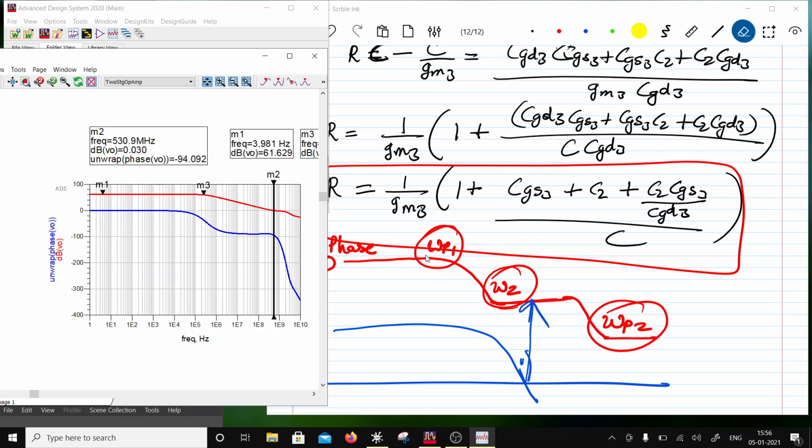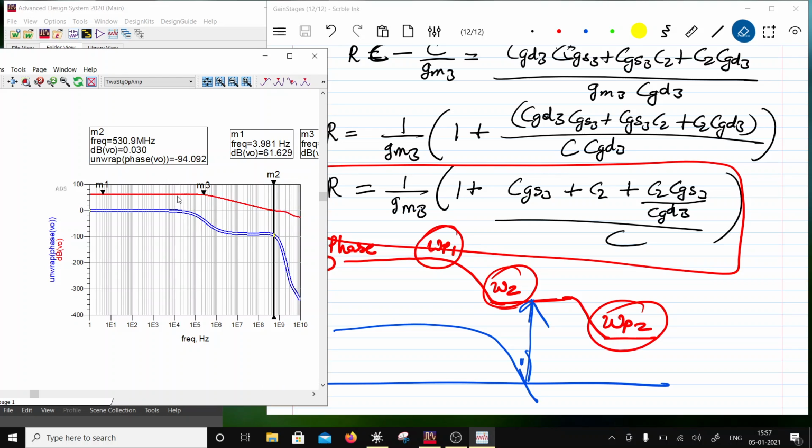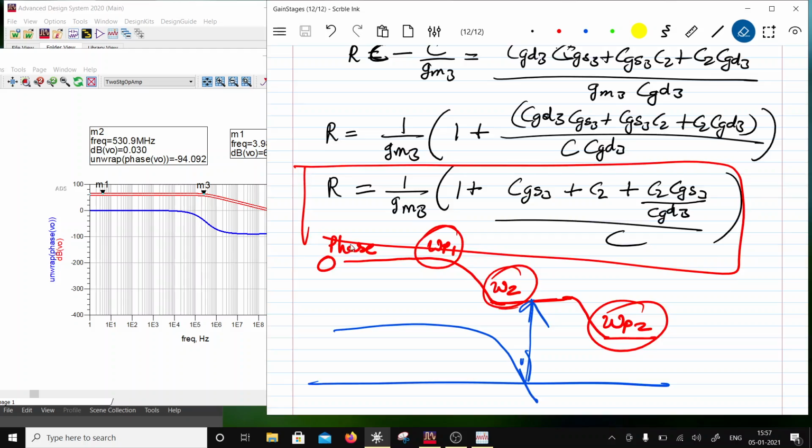So this blue one is this red one you see here. So this 90-degree over here is because of this pole P1, and then there is a zero which was introduced here, which caused this to be flat. So that became flat, minus 90 plus 90, and then the second pole came in here, that will be minus 90 again. Okay, so the blue one is telling you here the phase, and which is over here as the red one, and this is what the gain is doing. So before you hit the second pole, you want to get the crossover. Okay, so this is called lead compensation.